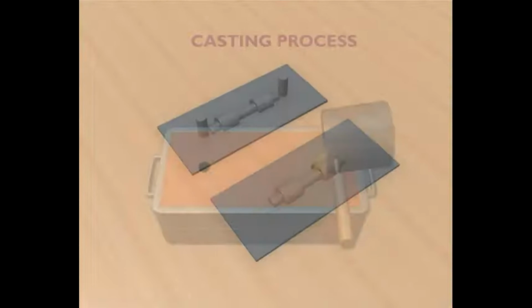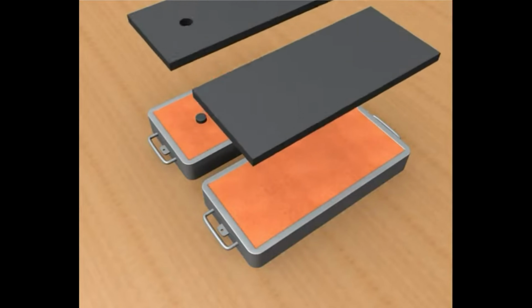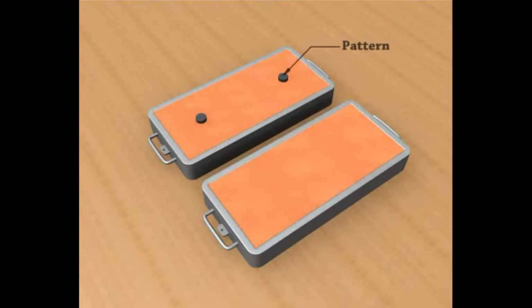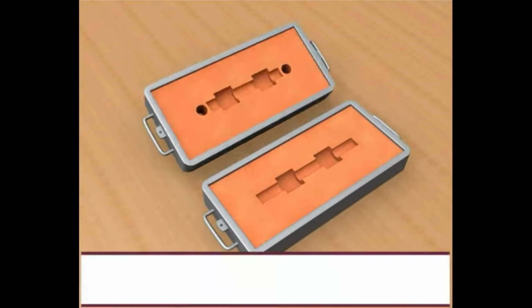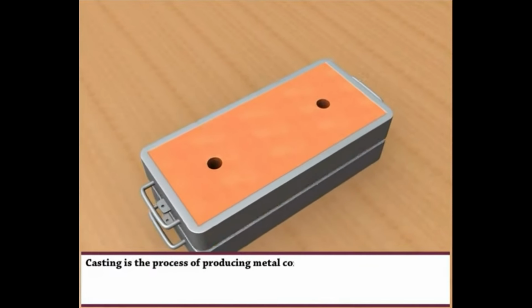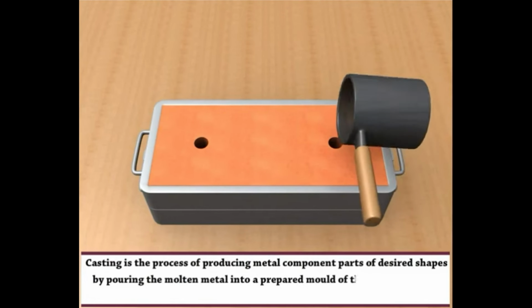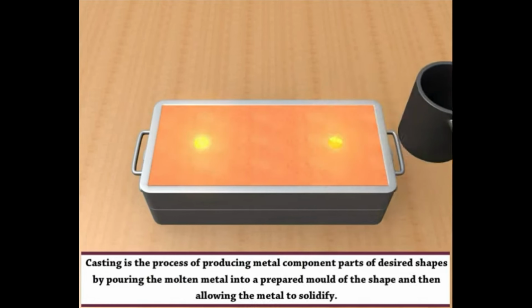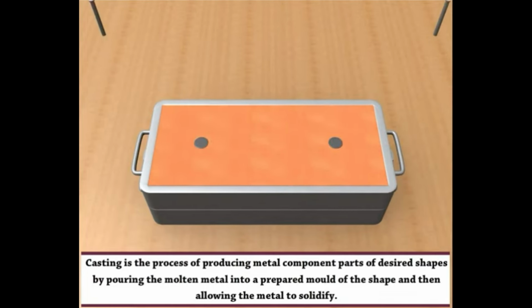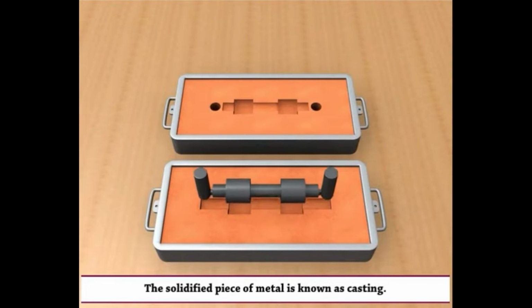Casting process. In this video, we are going to see about casting process. It consists of pattern and sand. Casting is the process of producing metal component parts of desired shapes by pouring the molten metal into a prepared mold of the shape and then allowing the metal to solidify. The solidified piece of metal is known as casting.